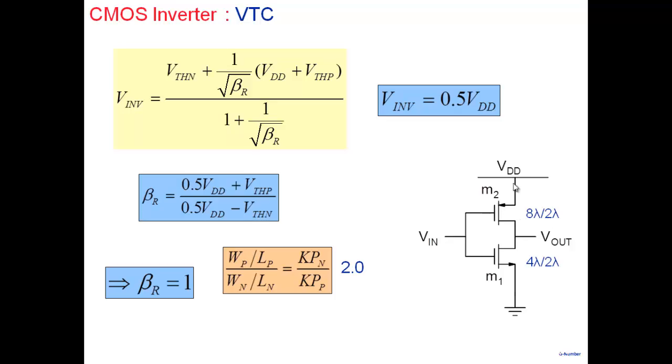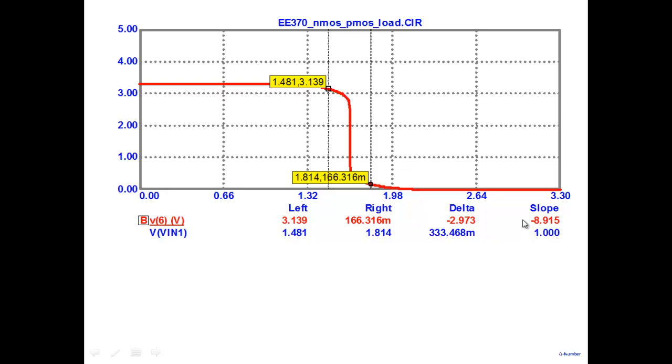Effectively, you can think of what you're trying to do as a very simple picture, you can think of it like a resistor here, and you can think of it like a resistor here. You're trying to balance the two resistors. That NMOS resistance is same as PMOS resistance. And if mobility here is half as compared to this, you're trying to increase the size of the transistor, because resistance goes inversely with the size of the transistor here. So this is what we obtain.